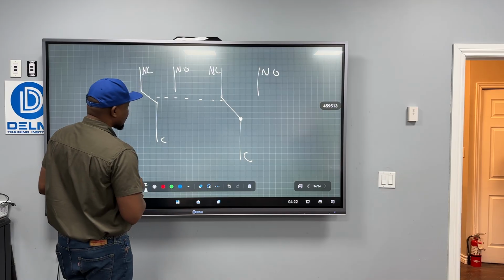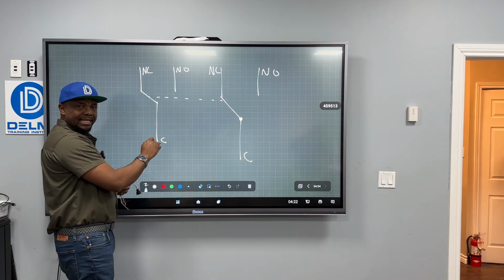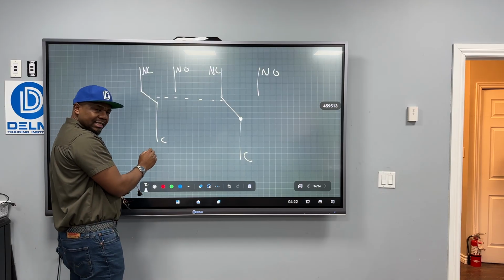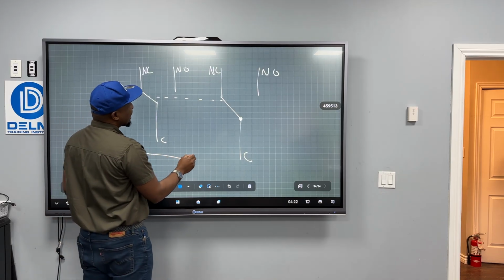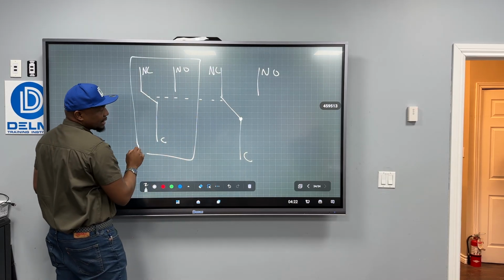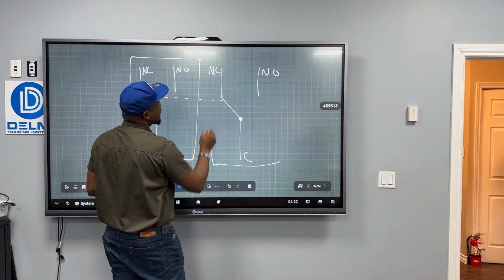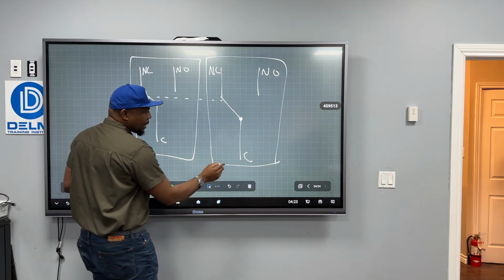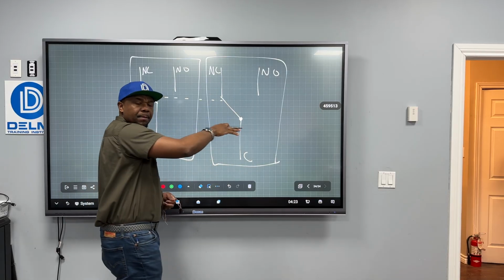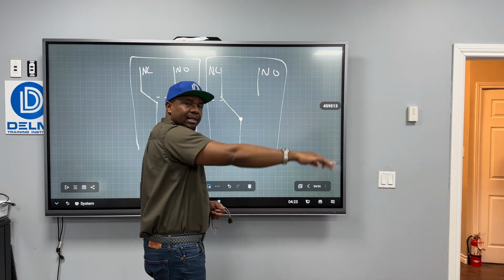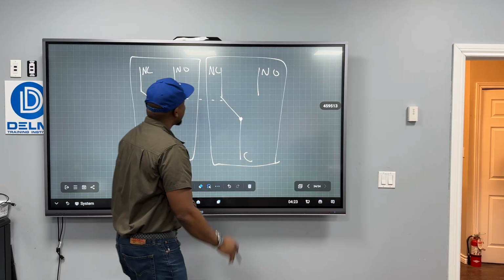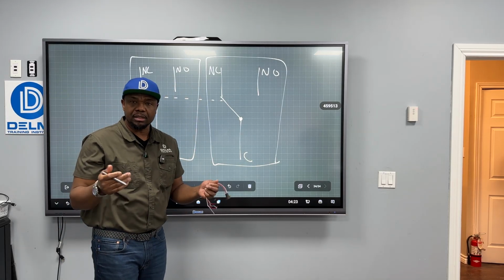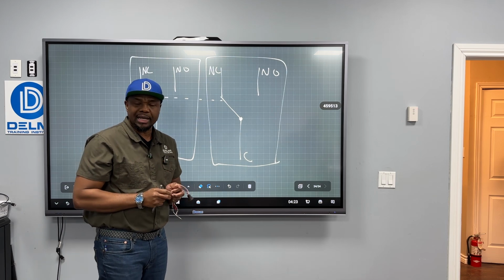Yeah. So because I have these, look at how they're going to act separately. I can decide to use this here as one circuit, and I can use this here as another circuit. Meaning that I can decide to connect this one to something, let's say an access control system, and I can connect this to my alarm or burglary system using one contact.